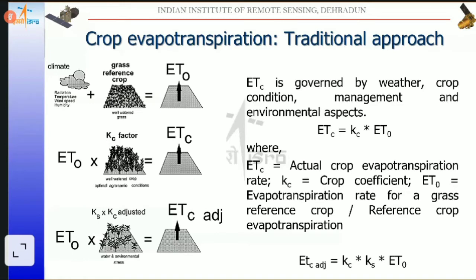The crop coefficient is simply the ratio of actual evapotranspiration to potential evapotranspiration. The Kc value is defined in the FAO Irrigation and Drainage Paper number 56 manual, which clearly and fantastically describes all its variability for the crop coefficient.